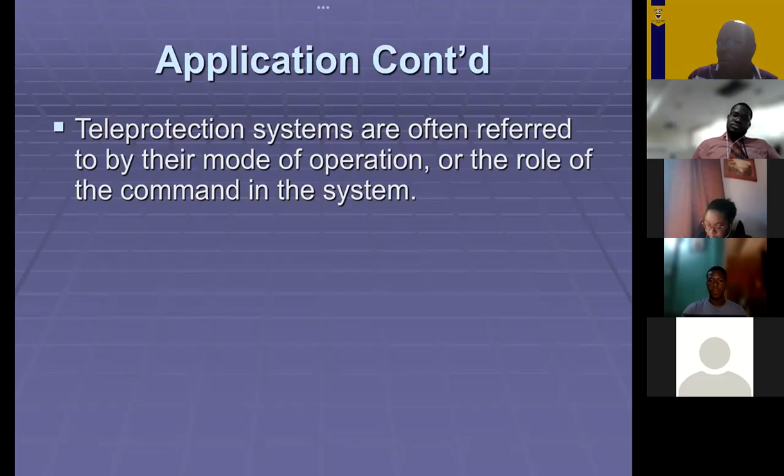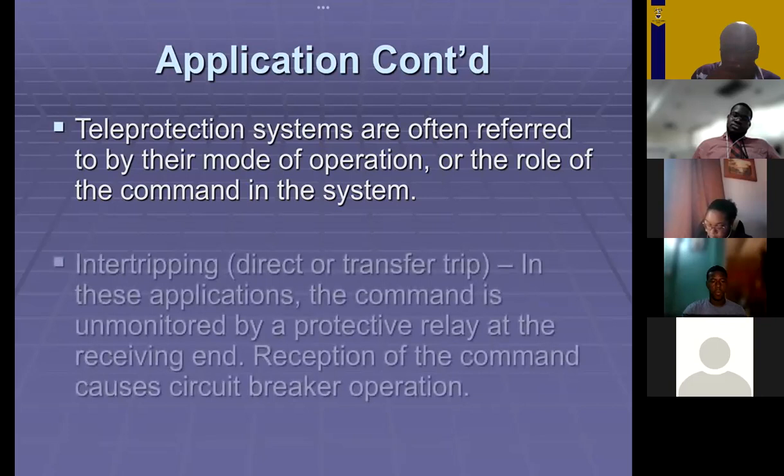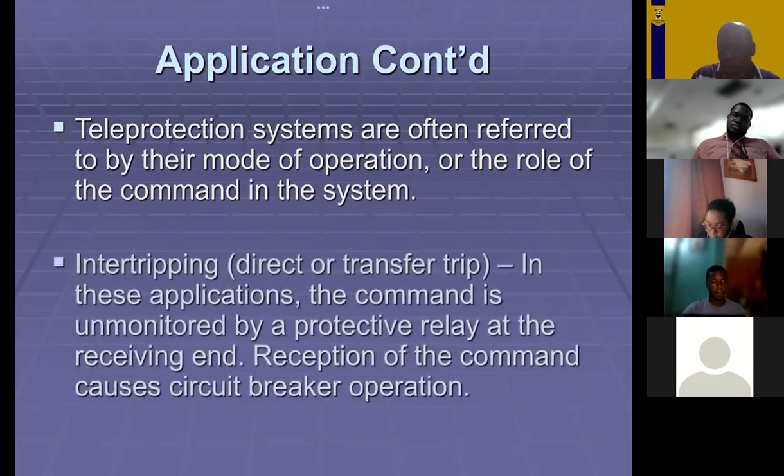So the teleprotection systems are often referred to by their mode of operation. And we went through this. I know I introduced them to you last week without getting into this. So we talk about your intertripping or your direct or transfer tripping. And this is where you're going to trip simply because you received the signal. So there's no monitoring.